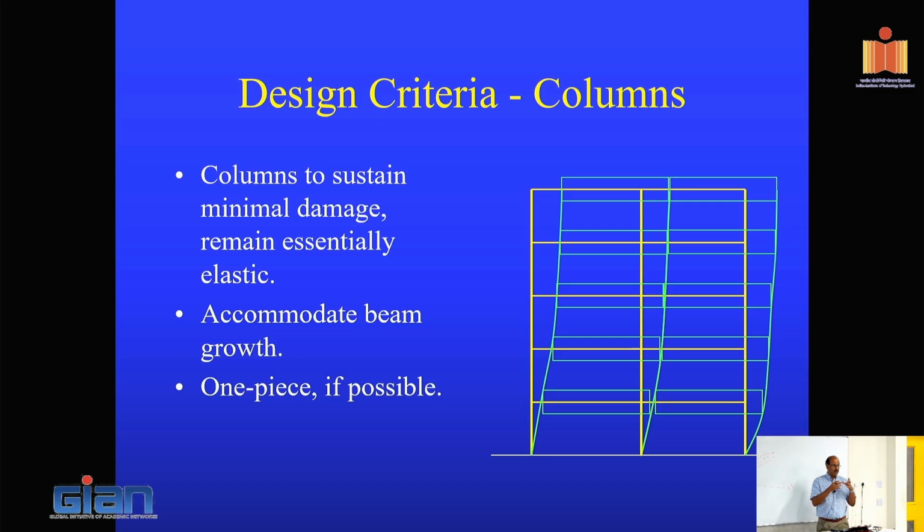Even in a cast and jointed system, the gap opens up, and you can appreciate that it has to elongate or grow in height in order to accommodate it. The structure will do this on its own, but if you have a floor slab, imagine in a wall situation, the wall has to go with it. And I will cover that a little bit more on Monday.